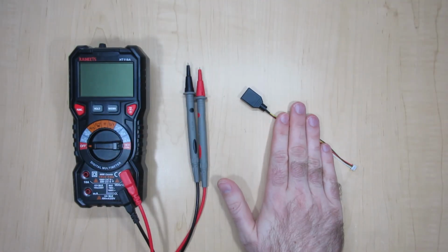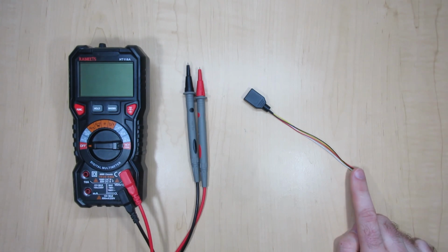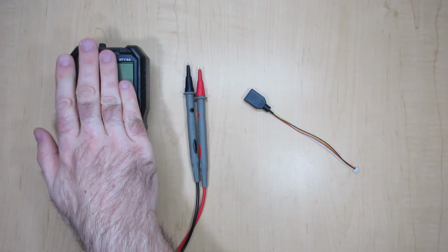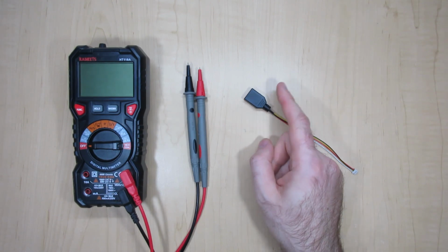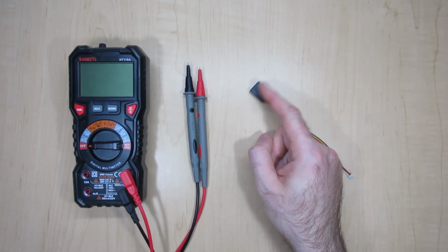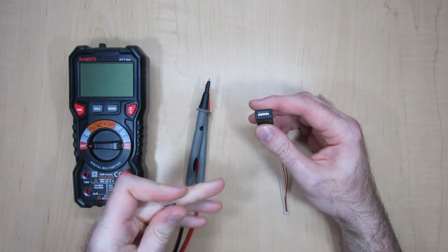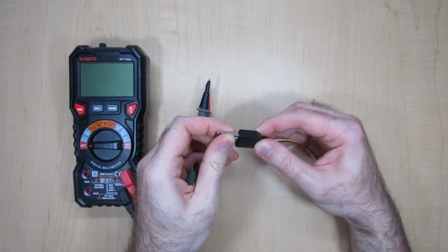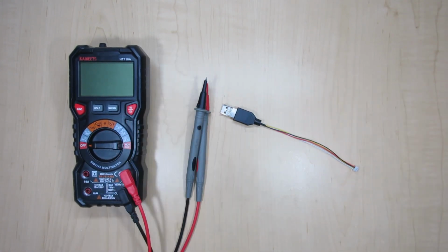My USB cable is ready, but I don't want to plug this into my computer right away. I don't know if I created any short circuits between the terminals on this end and the terminals on that end, or maybe even the terminals amongst themselves. So to test that out, I'm going to use my multimeter and validate the continuity between opposite ends of the cable and make sure that there's no continuity between sibling or parallel ends of the cable. I won't be able to get my multimeter probes into that female end of the USB side, so I have a male terminal which I'll just plug into here, and now the leads are exposed and I can test continuity between opposite ends very easily.